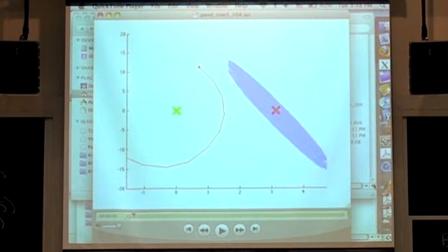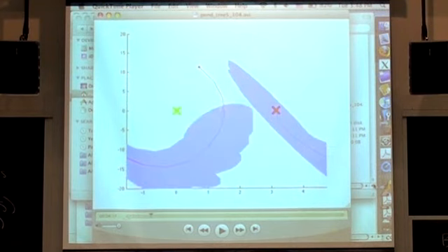And as we go, we'll compute the basin of attraction of that controller, which, I drew it in finite segments, but I hope you can see that's exactly the funnels. If I start the system inside any of that blue region, and I execute the LQR trajectory stabilizer along that trajectory, it's going to take me around and get me to my goal and stay there.